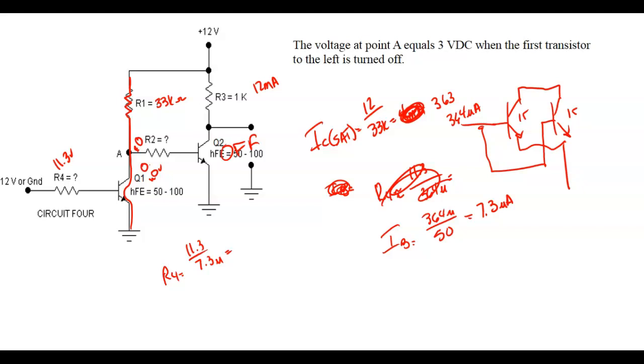And even though we got all this, you got to understand, I can saturate them, I can cut them off, saturate them, cut them off. So that's digital, right? So I can take the output of a PLC here that either puts out 24 volts or 0 volts, and now I'm getting microamps out of my PLC, but I'm controlling a big load. So the PLC, the programmable logic controller, everything inside is very low current, very low voltage, 5 volts. Usually inside the PLC we run on 5 volts.